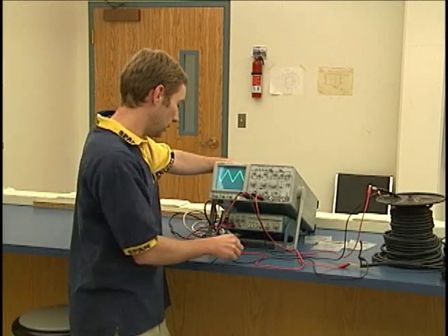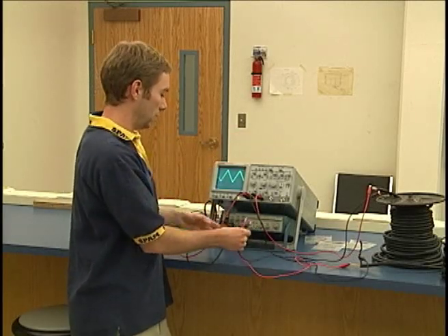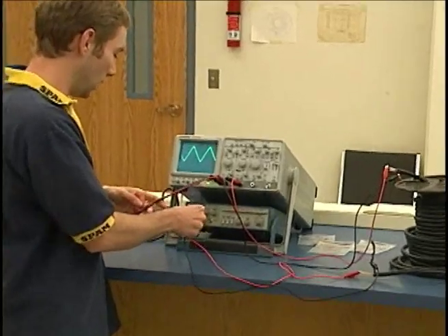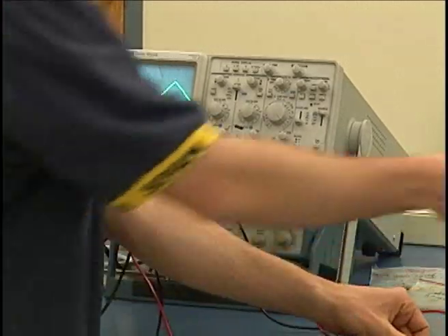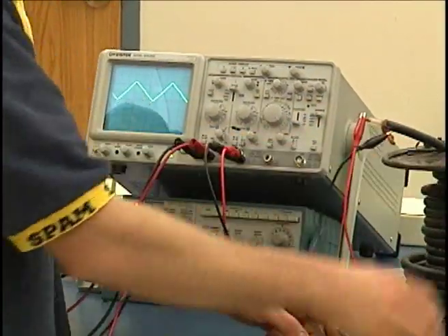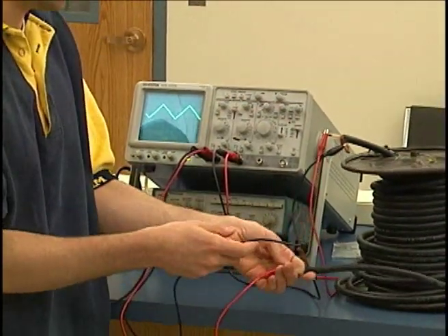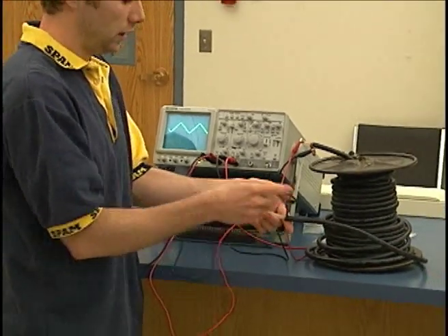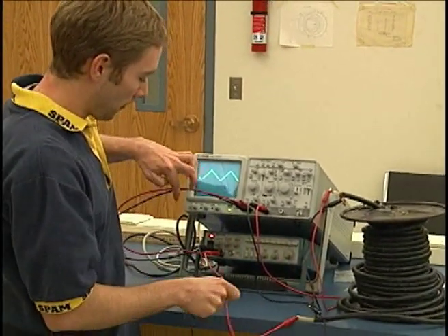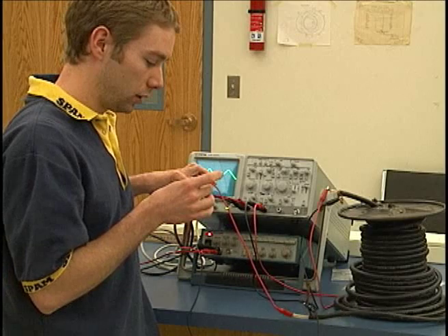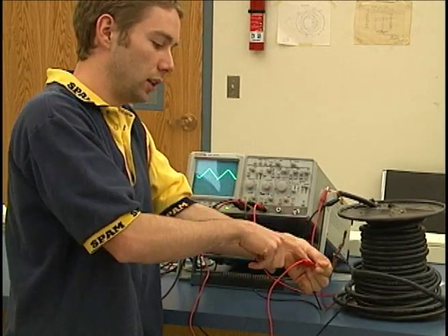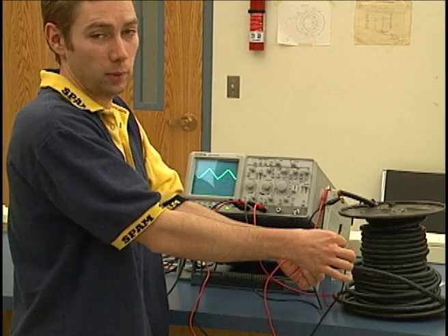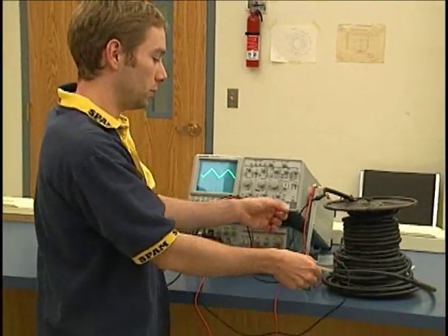Next thing you'll need to do is hook up this power source to have the signal going through one of these cables. So in this example, this is the RG8, which will be the same as RG58 for our purposes. And the way you do that is this. You'll hook the hot line up to either the inside wire or the outside. Doesn't matter which for our purposes, but just make sure that you're consistent.